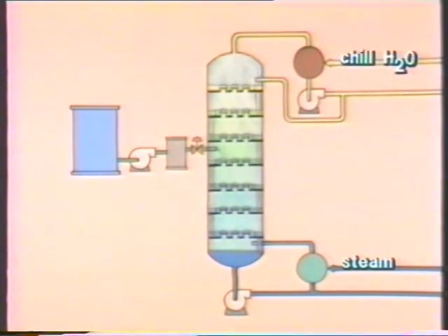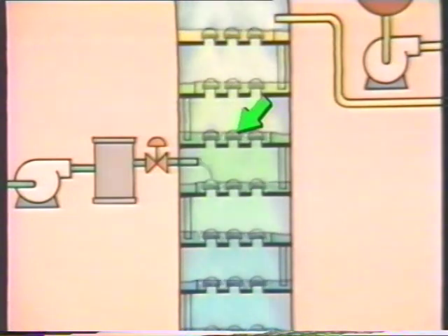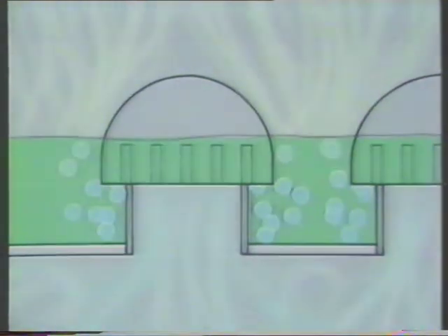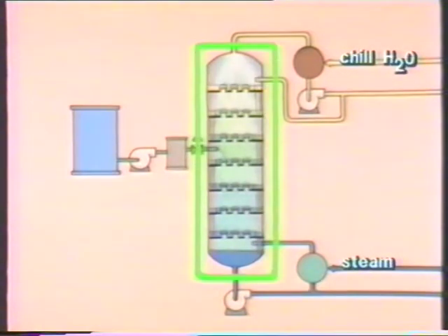The vapors that separate from the boiling mixture rise up and move toward the next higher tray. Each tray has holes, which are fitted with tubes called risers. The risers allow vapors from the lower tray to rise into the upper tray. Mounted on top of the risers are caps called bubble caps. The purpose of these bubble caps is to force the rising vapors to bubble through the liquid that has condensed in the upper tray. Distillation towers contain many risers and bubble caps. This is important because the rising vapors must make maximum contact with the liquid so that maximum heat transfer can take place between the vapors and the liquid.